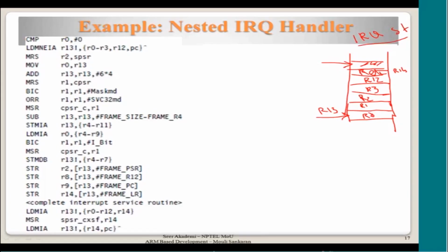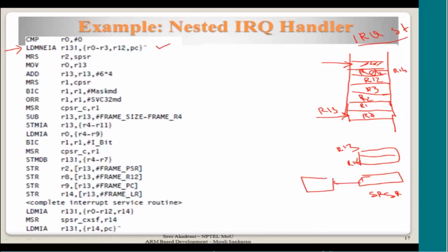So if there is no further processing required, it will execute this instruction. And IRQ mode has got an SPSR. IRQ has 2 registers, R14 and R13, and an SPSR, which happens to have the original value it should have. So R14 and R13 can be anything. It goes back by copying this into CPSR, and then it copies this value into PC, so it goes back to the original code. Now we are not interested in that part of the discussion.